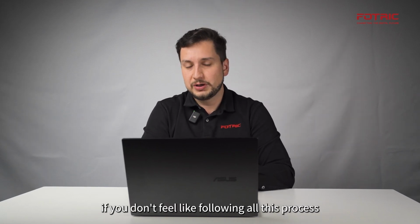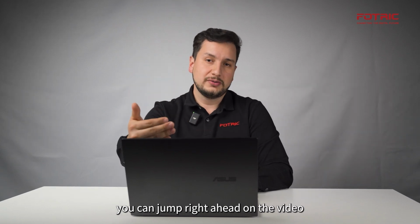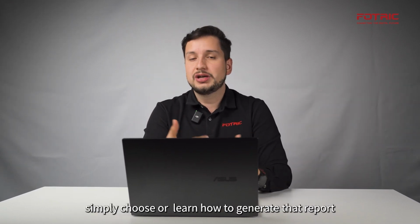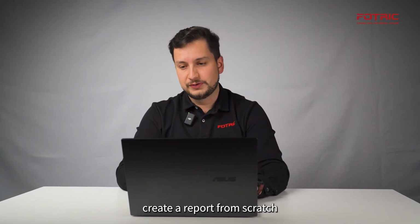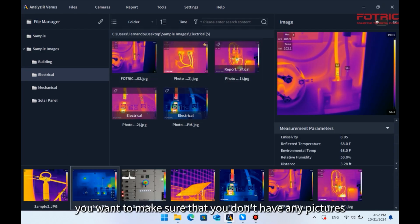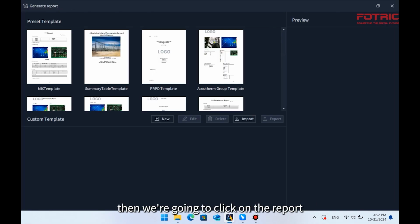If you don't feel like following all this process, you can jump ahead in the video and simply choose or learn how to generate the report. So let me close this and teach you how to create the report template from scratch. First, you want to make sure that you don't have any pictures selected. Then we're going to click on report, and this interface will allow me to either choose from here or to create one from scratch.